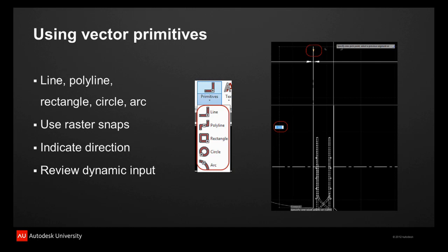There'll be prompts and parameters that you can play around with. It will try to identify a direction or a logical path to follow. If it's not able to do so, it's going to prompt the user for a bit more information, and you will have to specify the information as is required. In this case, I just used a simple line to start tracing those columns in the raster image, and you'll see at the top there, that's actually where I clicked, and again, use your raster snaps when doing so, then you actually start where you want to start tracing this image.